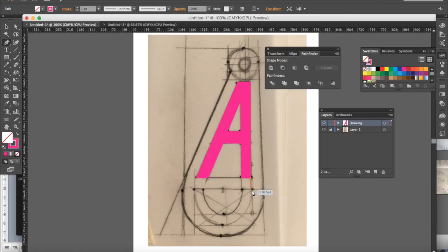We're going to go downwards. As you can see, it's sort of highlighted green, which means it's in line with that existing line. There's one anchor point. Now this time down here I'm going to set a second anchor point and click and hold the mouse down and pull out to achieve a curve. What's quite helpful is if you press shift, it will lock it horizontally, which can be quite useful. So I'm just going to try and create my curve there. I'm quite happy with that.